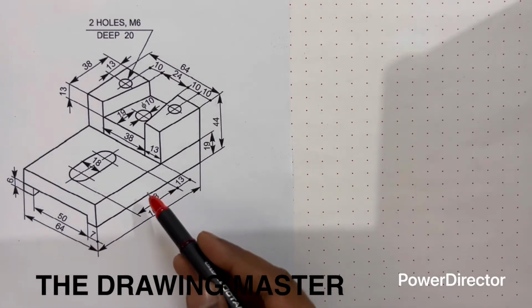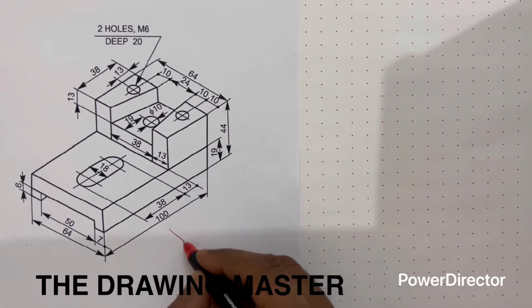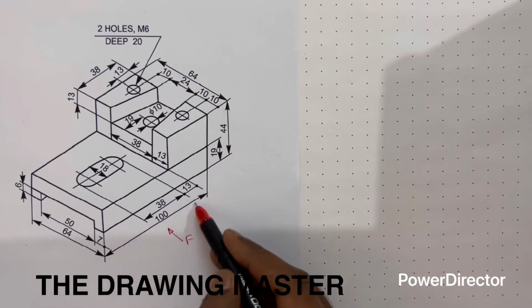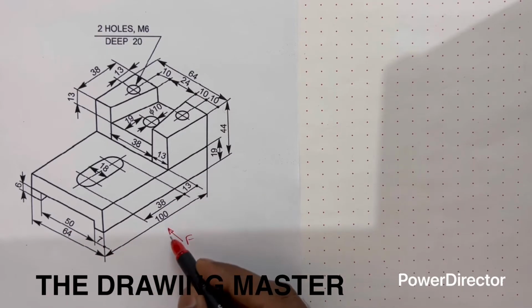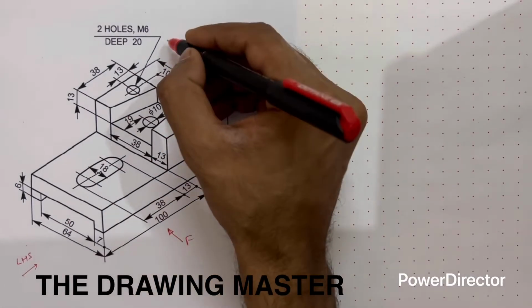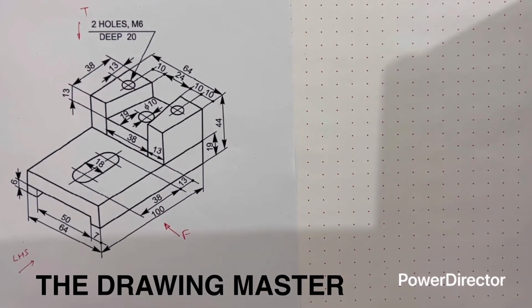In this drawing the direction of view for the front is not given. So let's say this one is the direction of view for front. The maximum dimension is the front view, right? If the direction of view is not given, you have to consider the largest dimension as the front view. So if this is the front, this will be the left hand side view and this will be the top view of the object. We have to draw its full sectional front view.